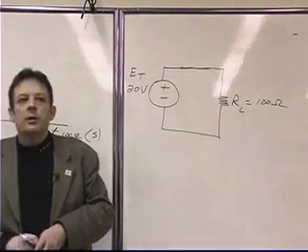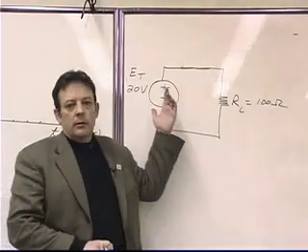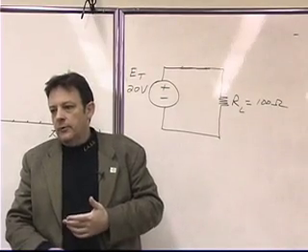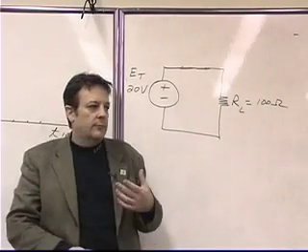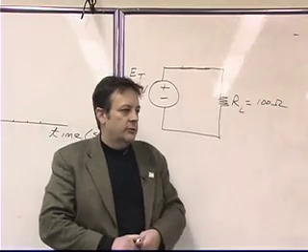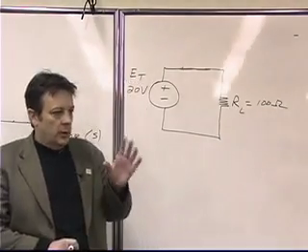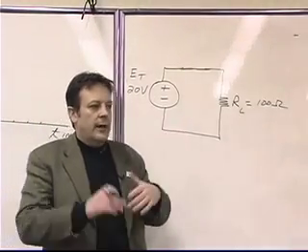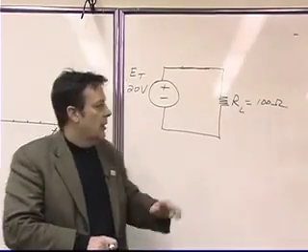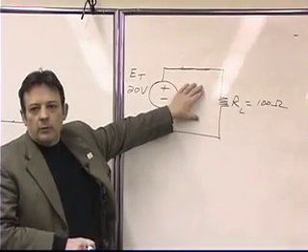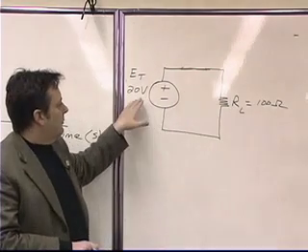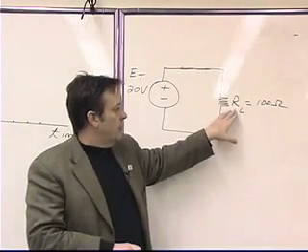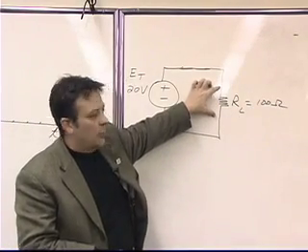With the exception that if you have a switch in a circuit, you're going to have some contact resistance. If you don't have a switch in a circuit, you're going to have no contact resistance associated with the switch. So there is a little bit of difference. But we're going to assume that our switch is an ideal switch and it has no contact resistance. So in this circuit right here, which is the DC circuit, we have 20 volts. What have we learned the voltage would be across this resistor if we put a voltmeter across it?